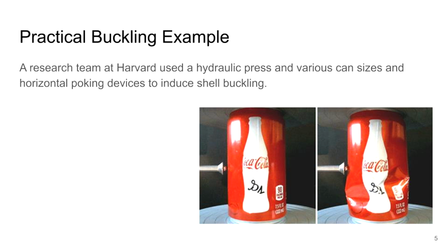The team clamped an undented empty Coke can between two metal plates to produce a force along its vertical axis. They then poked the side of the can using a metal ball attached to the end of a rod, continuously pushing the ball further into the can until it buckled with a loud snap. Repeating this measurement with various axial force strengths and ball sizes, the team mapped the conditions needed for buckling to occur. This map defines the can's "stability landscape," whose features indicate which combinations of parameters result in a crushed can and which don't.